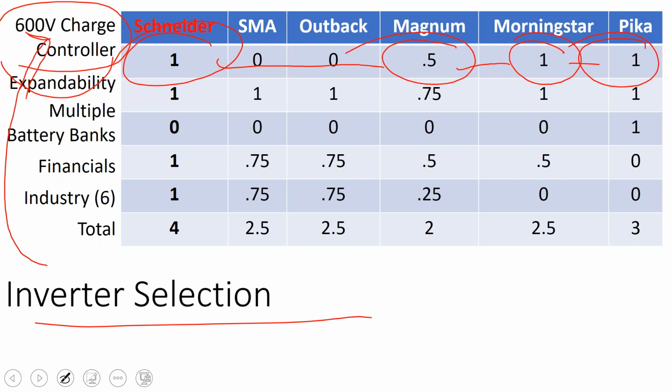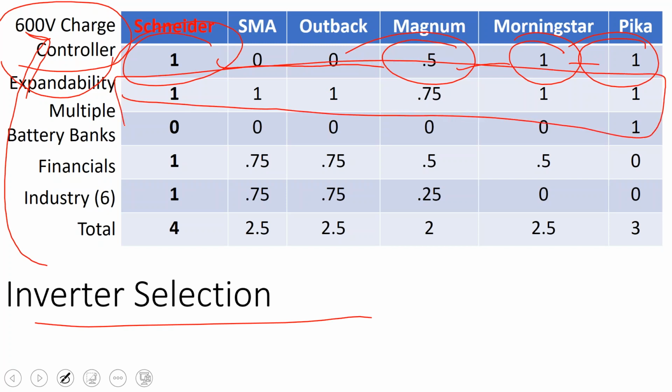If it was on the ground, if it was a smaller solar array, it would not have been that big of a deal. Most all of your inverters are scalable up to 200 kilowatts, so you can be double, triple, quadruple, quintuple stacking the inverters to make increasingly more powerful systems. You still have one inverter driving the whole system in kind of a master-slave electronics relationship. But most systems are expandable.